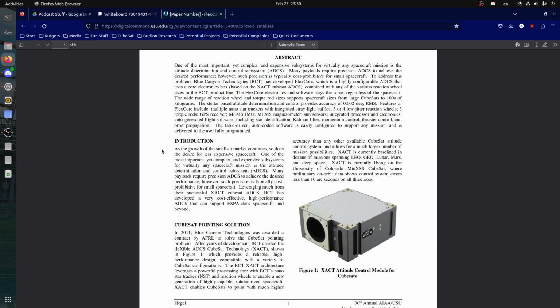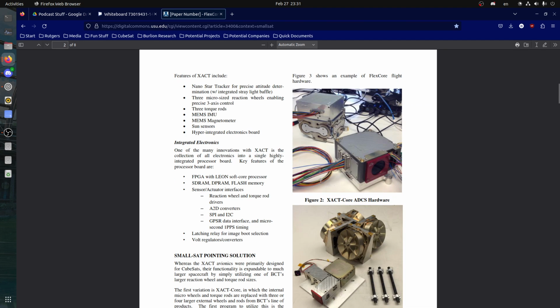It's an area of research on its own to see if that works, to what extent, and what the benefits and cons are. The cons would be you have to run magnet torquers constantly, and magnet torquers are just wires. You're just making a magnetic field. What are its effects on the electronics inside? If you have very sensitive equipment, a large magnetic field will mess something up. How reliable are they? What are the errors? How accurate can you be? What is the maximum torque you can generate? All of those are questions that I know people are working on, but I don't have the exact answer.